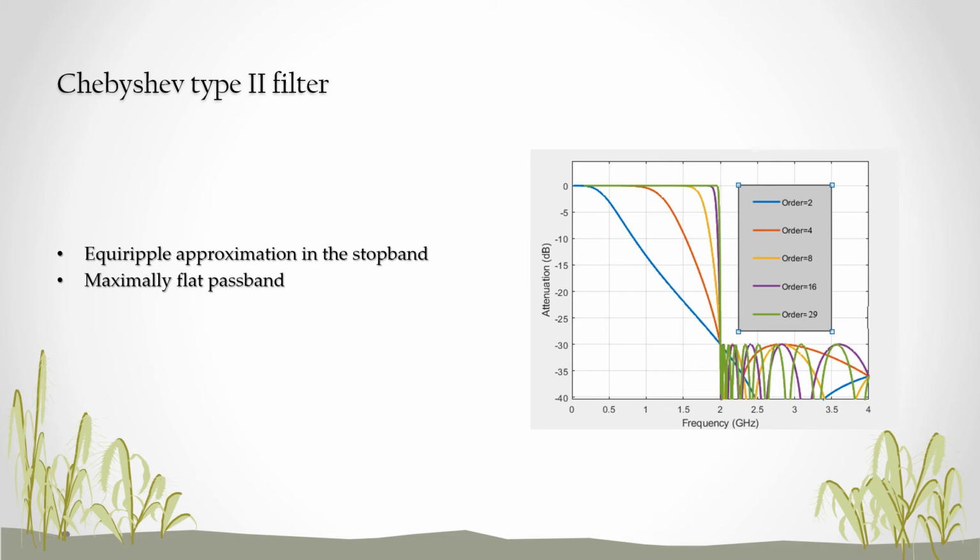It should be noted that increasing the order of the filter decreases the width of the transition band, but then a signal with a higher number of ripples in the stopband occurs. The number of ripples in the stopband determines the filter order.